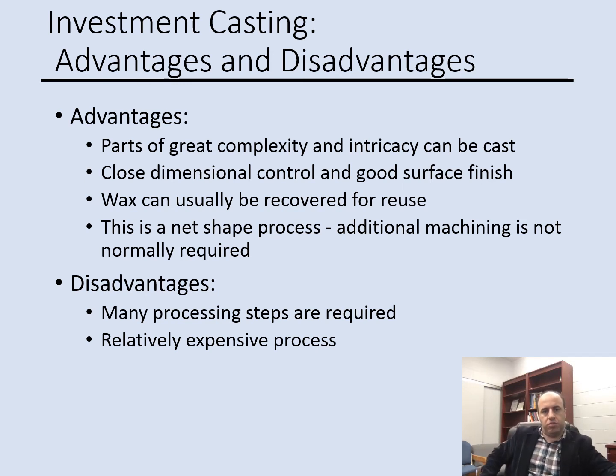Disadvantages are you need to go through several steps to make the mold. So this is not an advantage. This is one limitation. It takes some time to make the part, to make the mold ready, and it is an expensive process. It's again similar to the previous process, shell molding. This is not recommended if you want to make one part, two parts, less than 10 parts. You should use the process for at least 1,000 parts.